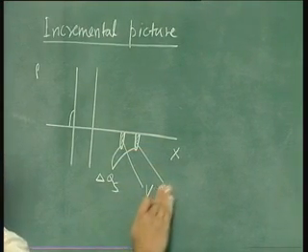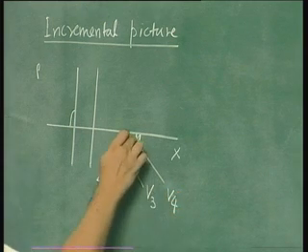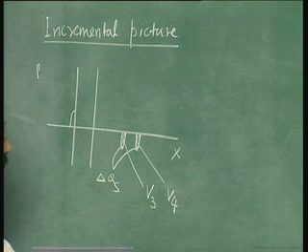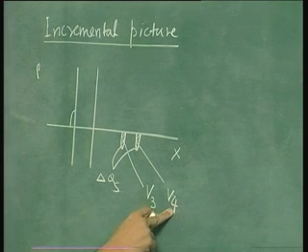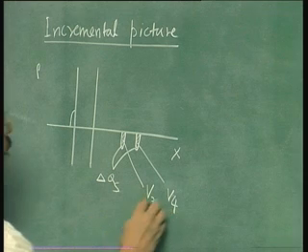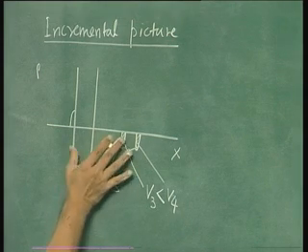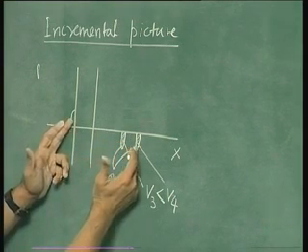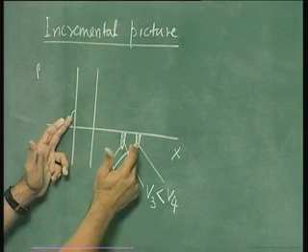So supposing you call this voltage V3 and this voltage V4, this V4 is on the verge of just below threshold, okay. So we are following our nomenclature, suffix 4 was always supposed to be near the threshold. So V3 less than V4, this is the increment in the charge. So this explains why the capacitance goes on falling, because this distance between the incremental charges is falling, okay, and this is what is the capacitance.